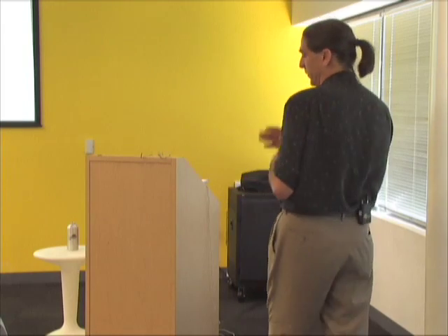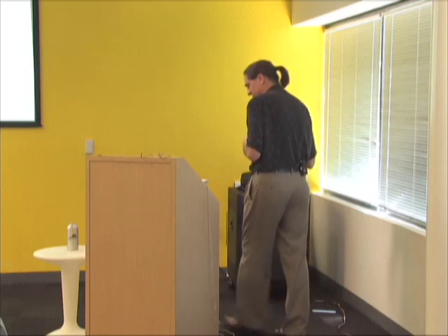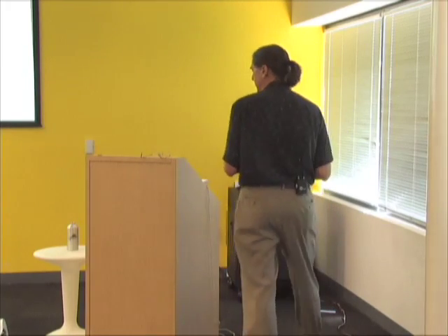I only put the zero in front because I like those grouped. Those grey layers are the nest holders, to be high up on my list, because I don't like filtering through and trying to turn things off deep down in the model. This is a huge piece, and once you get the knack of it, it really will simplify how you use large models, because you can turn off everything but what you want to work on. You can flip it on and off.